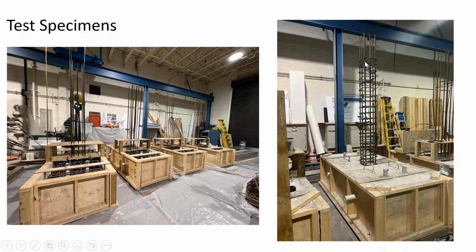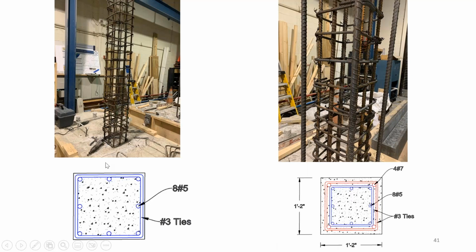We have also, and these are very recent, been retrofitting columns. For example, here you see an existing column, and we are adding some additional reinforcement and then wrapping it. In one specimen we use normal strength concrete to increase the dimension of the column, and in another we use the UHPC. So this is going to be a very interesting test, but it's coming. We've got several specimens geared toward strengthening existing columns by adding additional reinforcement and wrapping them with the UHPC.